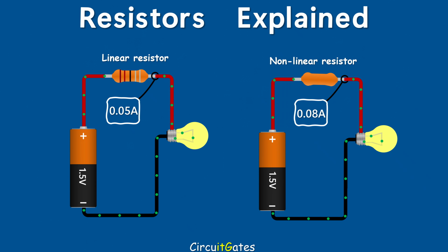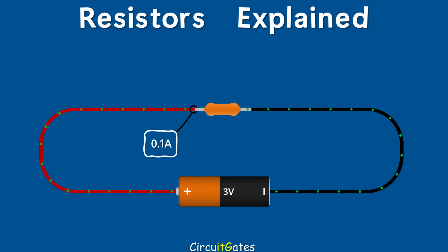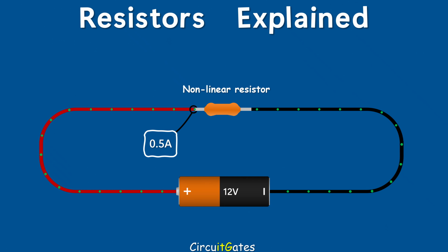A resistor is linear if current through it proportionally increases or decreases with the voltage, but if not, it is a nonlinear resistor. In Ohm's law, temperature is kept constant, since the resistance of all resistors is affected by temperature. In nonlinear resistors, even when the temperature is kept constant, current does not proportionally increase or decrease with the voltage. This is because they have other conditions that affect their resistances. There are also resistors with resistance value that significantly changes with a change in temperature. These resistors are also put into a group of nonlinear resistors.